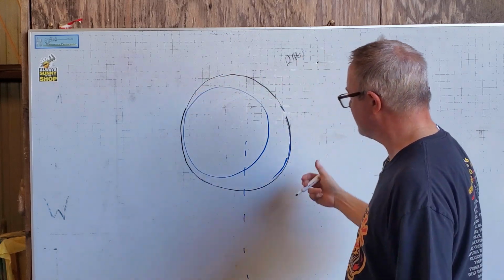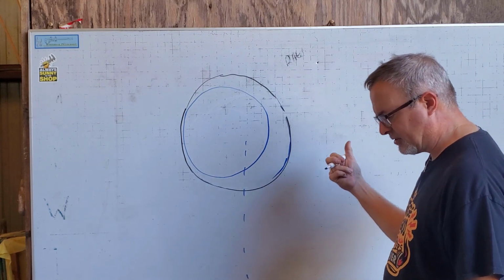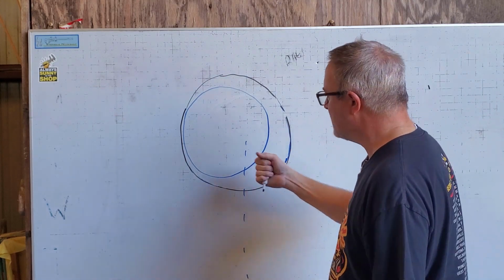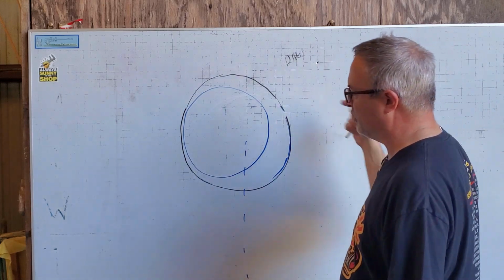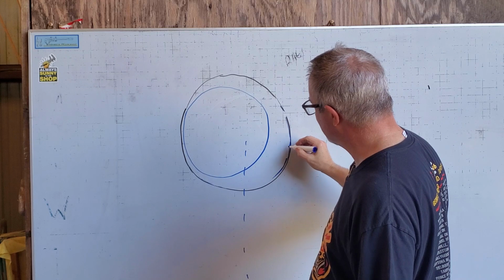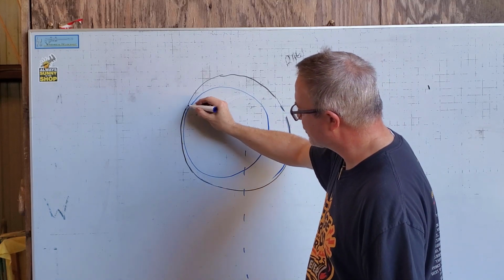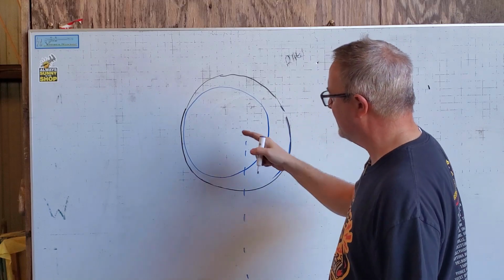This is where the energy of the moving piston, connecting rod, crosshead slide begins to pull on the crank and put energy back into the system. So now we've taken the oil film, which was compressed on this side, we've swapped sides, and now we're squeezing the oil film on the back side.